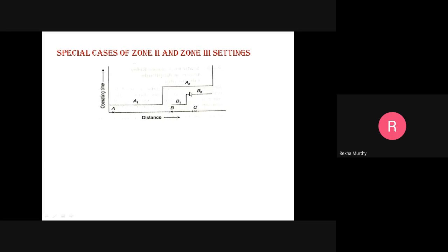It is almost covering up the entire two sections under the zone 1 itself. So this is how the zone 2 settings has been done. So zone 2 is totally depending upon the zone 1, which has covered the entire region by the zone 1. Okay, so this is how you can avoid the overreach conditions.